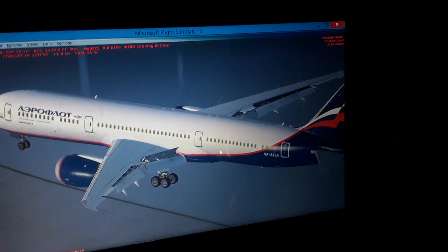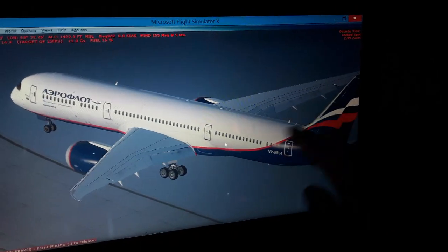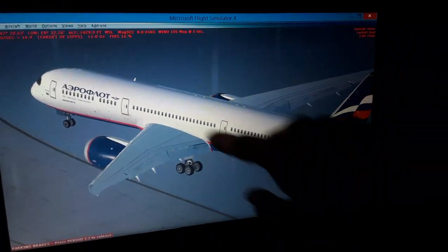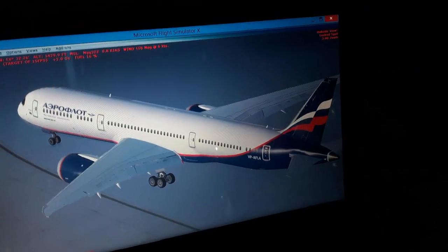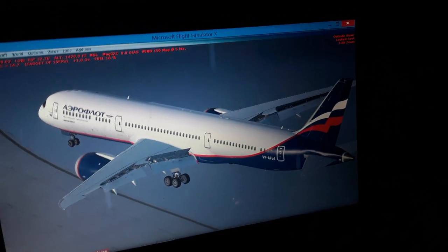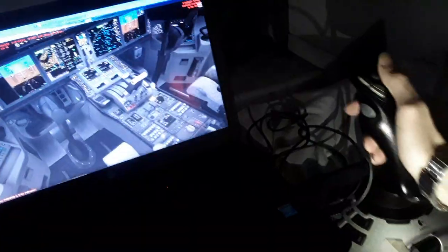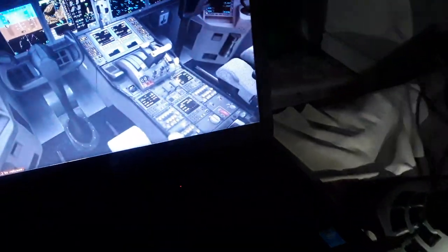So we have higher pressure below the wings when we fly. Also, you can see the top surface of the wings is more curved. There is a higher curvature above the wings. So using Bernoulli theory of fluids, the airflow moves faster above the wings. So there is lower pressure, which sucks the aircraft weight and wings up into the air. So that's the basic aerodynamics, aerospace and aeronautical engineering and Newton's physics, Bernoulli theory of fluids, all we need to know for the air transport pilot license. So you can see also here. I'll show you now the flight controls, perhaps how to use them.